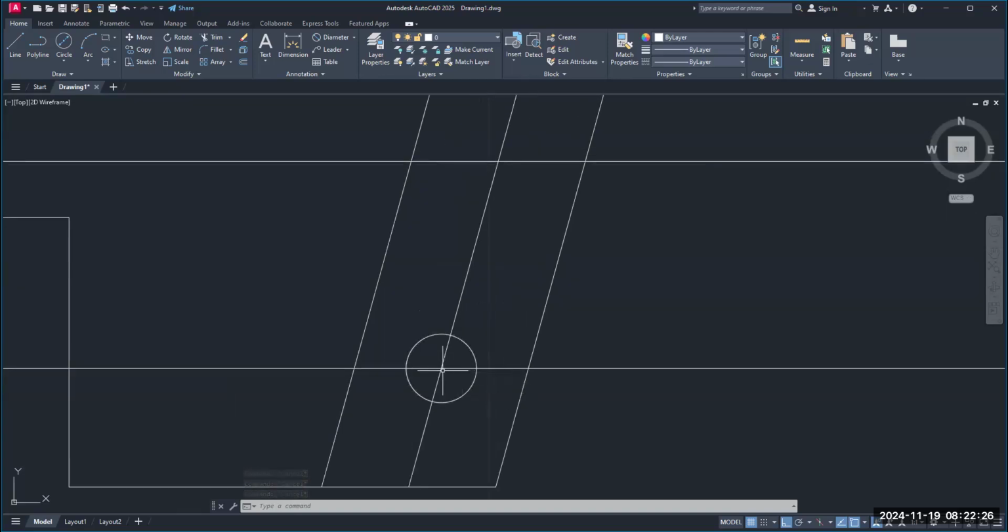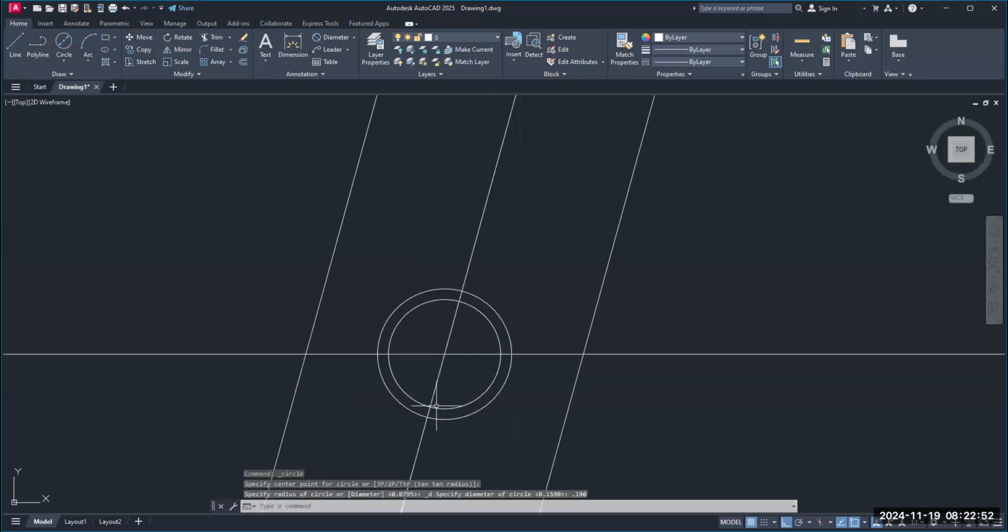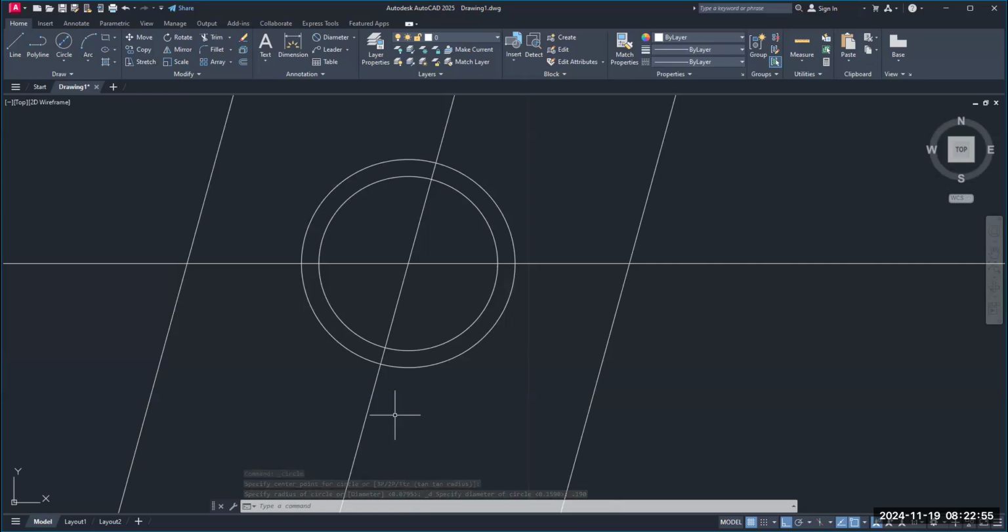Now we're going to draw another circle using the same center. So it would be concentric circles. Go to circle, go to center diameter, and move your cursor over here to the intersection. Click, drag it out, and we are going to make this diameter 0.190. Enter. Now, Mr. Morris, what do these two circles mean? This is a good time to explain. This circle here is actually the tap drill size. This circle here is actually the major diameter of the thread after you've tapped the hole.